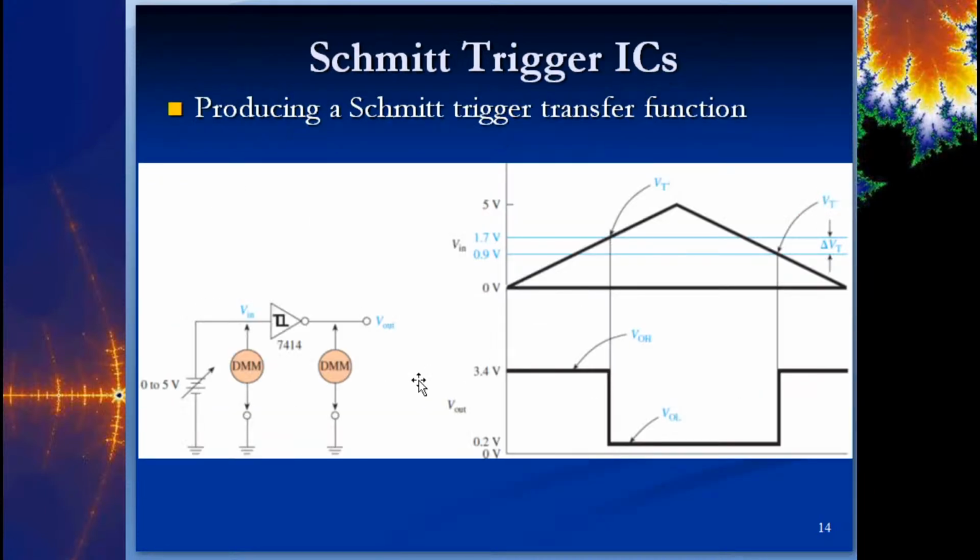All right, so here's another way to look at it. We're looking at the signal before it gets to the Schmitt and the signal after it's out of the Schmitt, so the input and the output here. If we have a triangle wave input that climbs, you can see that the positive going threshold is when it switches. It comes to its peak and comes back down. It doesn't switch here. Where it hits the positive, it has to hit the negative going threshold, and then it switches.